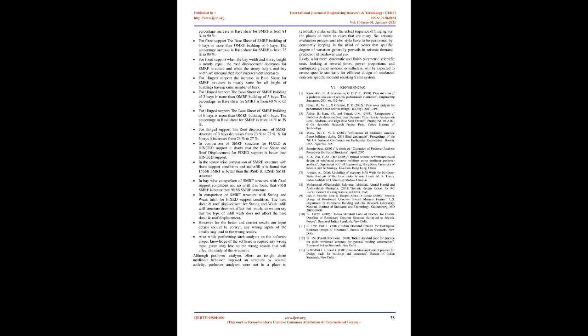In bay-wise comparison of SMRF structure with fixed support conditions and no infill, it is found that 9S6B SMRF is better than 9S3B SMRF structure. In comparison of SMRF structure with strong and weak infill for fixed support condition, the base shear and roof displacement for strong and weak infill wall structures are not affected much, so we can say that the type of infill walls does not affect the base shear and roof displacement.